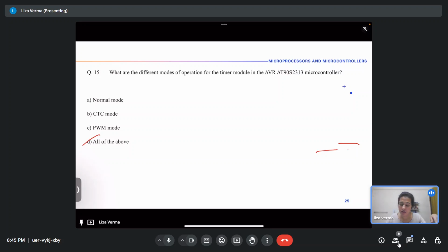And there's another kind of instruction, reverse subtract. In reverse subtract, it will give the reverse answer. Normally, if it is R0 comma R1, the result will be R0 minus R1. Reverse subtract is a three operand instruction. So RSB R0, R1, R2: the result will be stored in R0. In normal subtract you will get R1 minus R2, but here you will get R2 minus R1, and the result will be stored in R0.